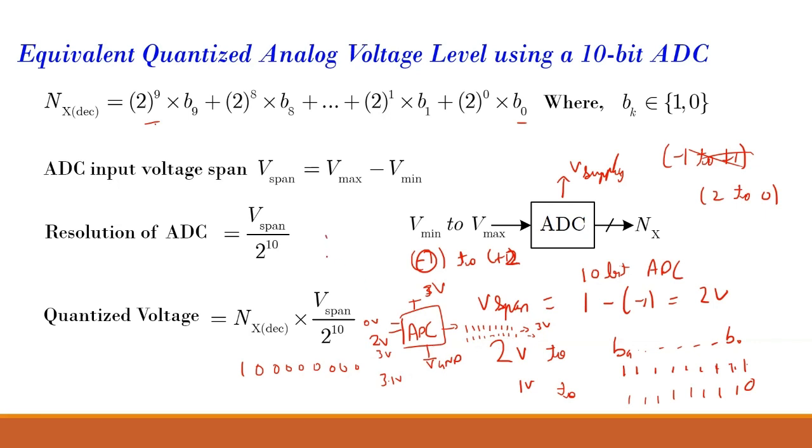See, these are all ICs. They have all these pins, etc. They are very sensitive. They have some particular range in which you can apply values. That range could be dependent on the supply voltage. It could be that only V supply plus 0.1 volt, etc., is tolerable at that pin. If the voltage at that pin goes higher than this value, then that pin will get damaged. If it is damaged, the IC is gone.